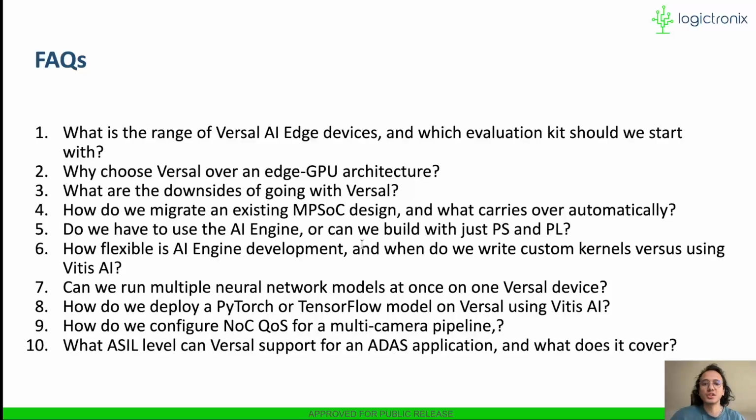We also get deterministic low latency because ML workloads run on the AI engines and sensor pipelines can run on the dedicated PL, so the worst case timing can be bounded. We also get the adaptability because PL fabric lets us build any sensor interfaces or custom pipeline logic for our specific application in the hardware itself without accepting a fixed set of interfaces.